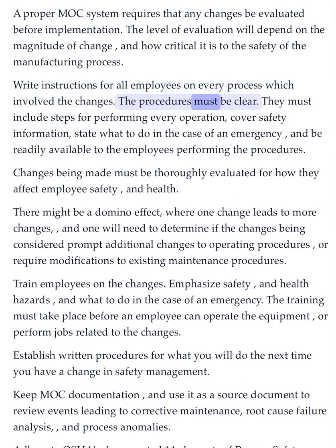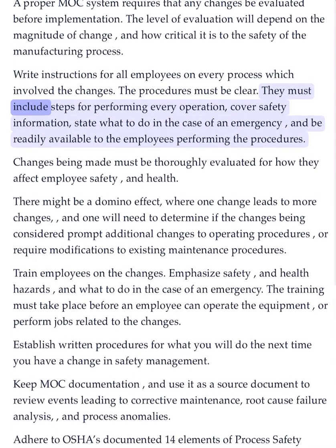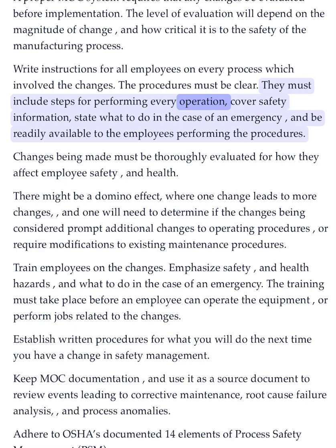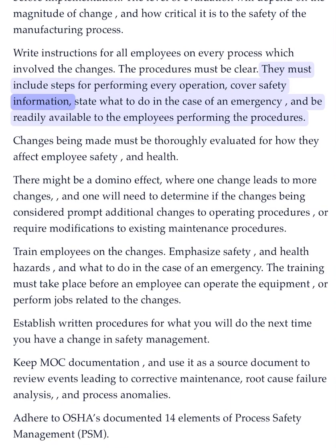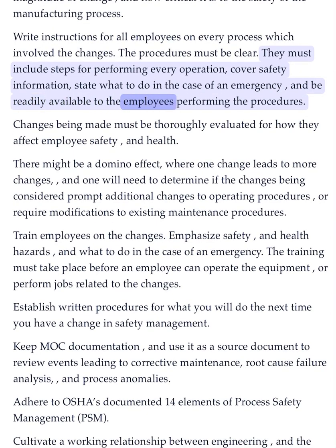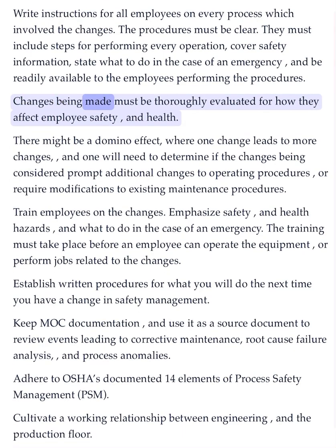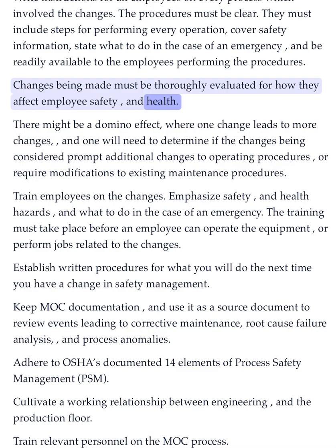The procedures must be clear. They must include steps for performing every operation, cover safety information, state what to do in the case of an emergency, and be readily available to the employees performing the procedures. Changes being made must be thoroughly evaluated for how they affect employee safety and health.